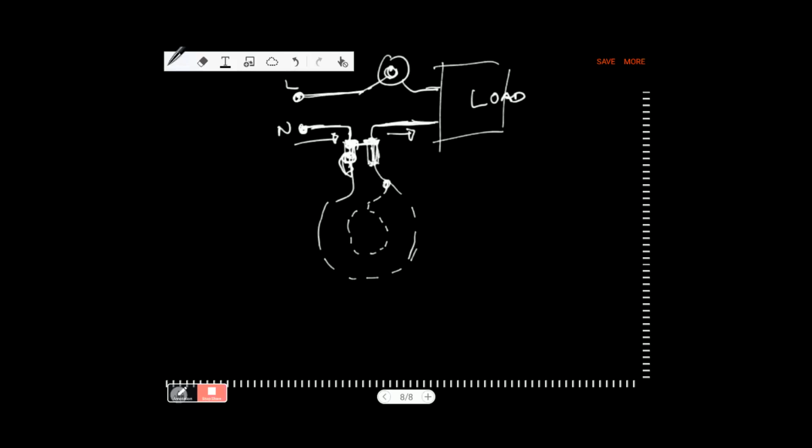Okay, this is this way. So the connection is on the top. But we have to verify first in this configuration. I don't have my copy here, which allows. So the ohmmeter will verify which part of this will allow the flow towards the other, this way or this way. So make use of your ohmmeter.